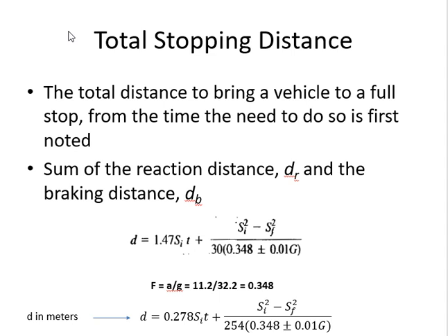And you will put the speed as what? Kilometer per hour, because the distance is in meters, so speed should be in kilometers per hour, and when distance is in feet, the speed is in miles per hour. Clear? All the conversions are there. You don't need to do any conversion yourself, just pick the right equation and put the speed as it is. Clear?